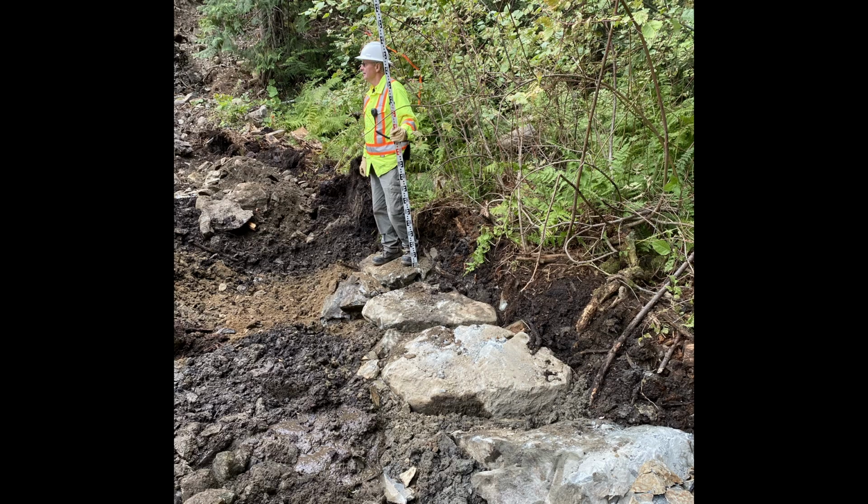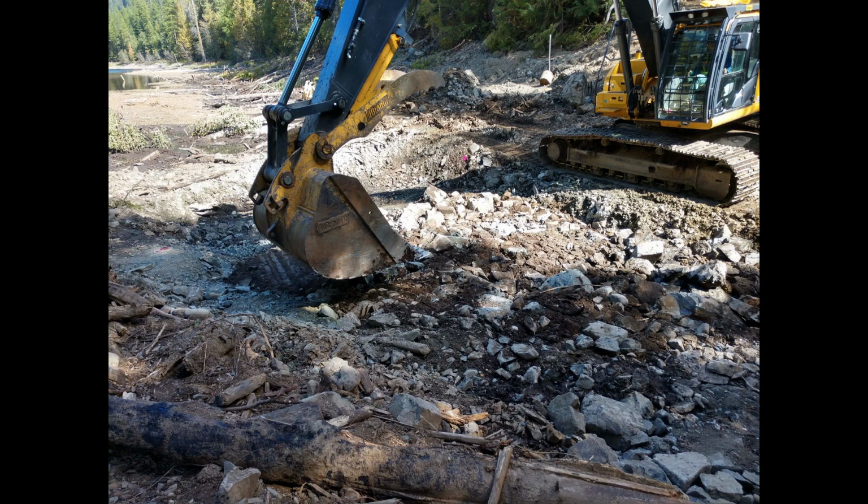We're using these large rocks to fill the trench to build the buried vertical grade control structure. I take elevations with a dual-sided grade rod and a laser level to see if the top of the boulders is too high or too low. The excavator now places a thick layer of rock that will span the width and the length of the floodplain for the restored section of Goodeve Creek.